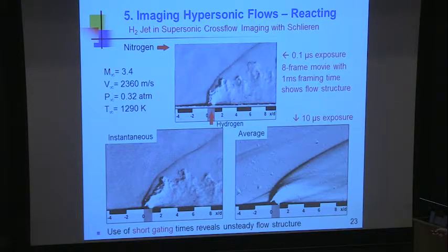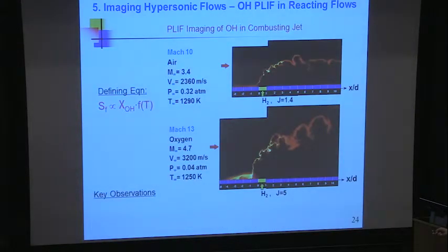But when you do this at high speed, you find out that these flows are not as steady as you think because of the intermittent structure of this mixing here. This is a burning mixing jet. There's the instantaneous structure revealed by Schlieren that causes this wave to not look like the textbook pictures. So the virtue of this high-speed camera in this cross-flow problem relevant to the scramjet was to reveal that these flows are not really steady.